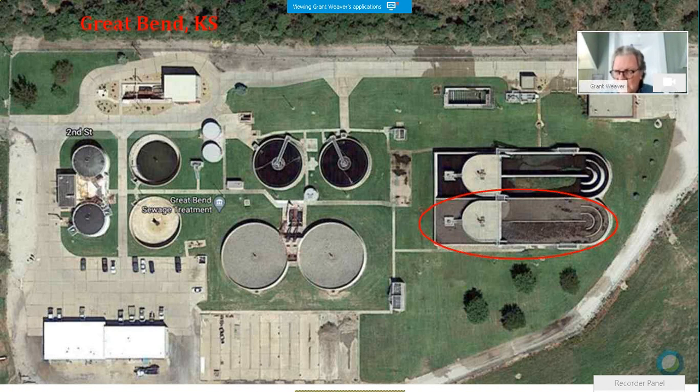Then they took, let's see, my little picture, that would be in that zone, and then what was the anoxic zone is designed for nitrate removal. They don't need to remove nitrates there, it's already being done in the ditch. So they turned that mixer off, which is right there smack in the middle of that circle. There's a vertical shaft mixer. They turned that off except for less than an hour a day. And that zone has become sufficiently anaerobic that they've got 2 or 3 months now of very good phosphorus removal out of a plant that really never was removing phosphorus.